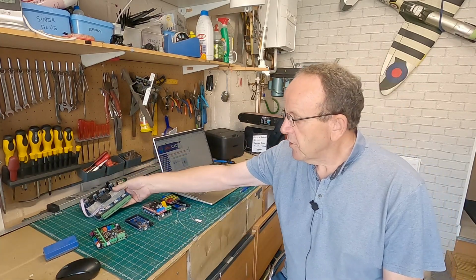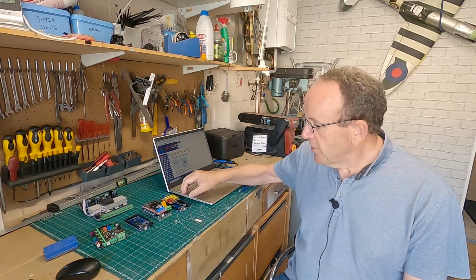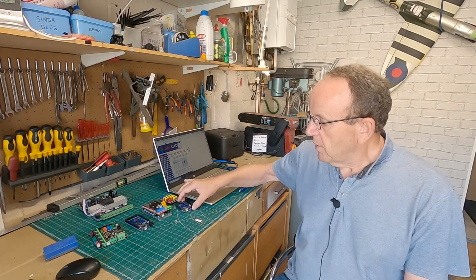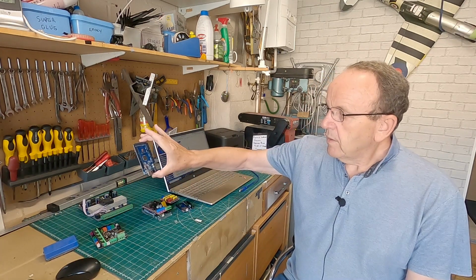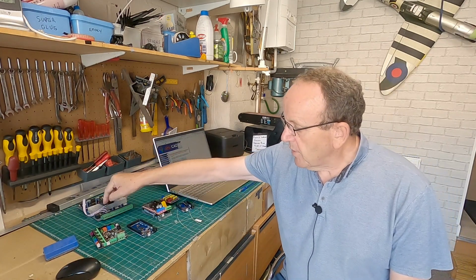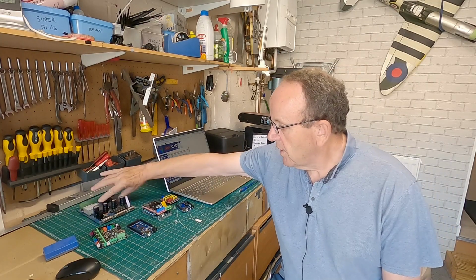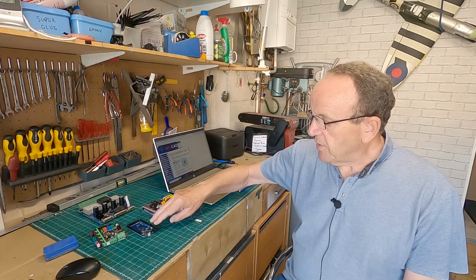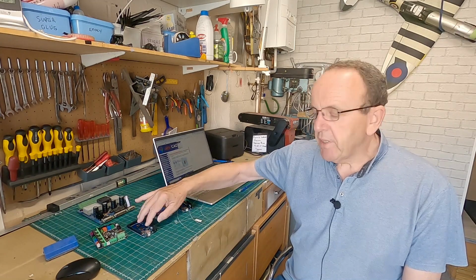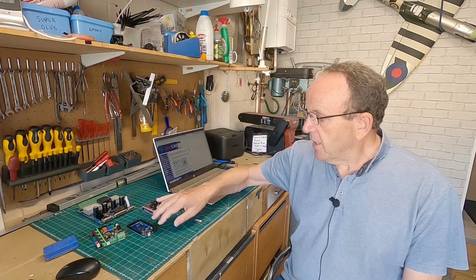Well, one of the things you can do with DevCNC Foam, you can actually hook up a Uno or a Mega up to the old parallel port. So if your old parallel port computer has suddenly died and you can't get hold of another one, or you don't want to get another one, what you can do is have this as really like a USB interface into your old parallel cutter. So it gives you all the wiring.